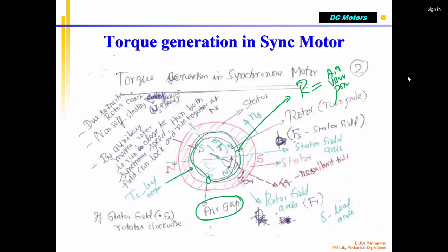Please know that in the rotor and stator, once current is flowing, there will be I square R loss, which is also copper loss. Correct? So the resistance of the coil, whether stator coil or rotor coil, multiplied by the current flowing, I square R, that much heat will be generated. If you see the end of the motor, there will be a fan. Generally, for protection, they put a cowl so that you will not touch it. But in any bigger or smaller motor, you will see a fan rotating on one side, attached to the rotor, or the armature in a DC motor. So air will be sucked in and flow through this gap and cool the motor. On the other side, you will see the hot air.